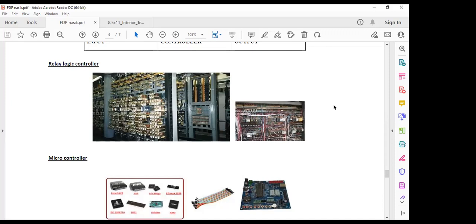So we open that control panel box. We take a communication cable of the PLC. One end we connect to our laptop, the other end of the cable we connect to the PLC. Now we open the PLC software. In the PLC software, we have the option receive, and we call it upload also. See, in a microcontroller, upload means you are sending a program. But in a PLC, upload means we are receiving. So I shall use send and receive.